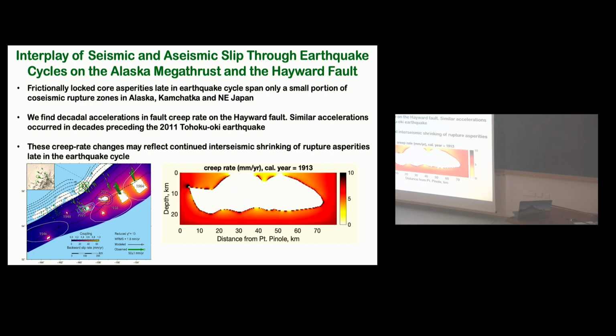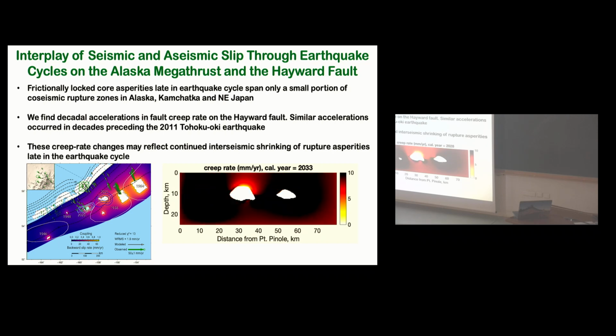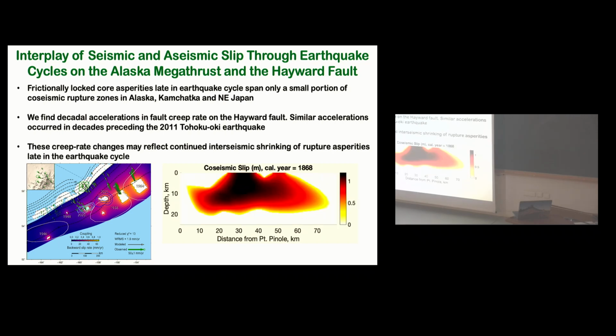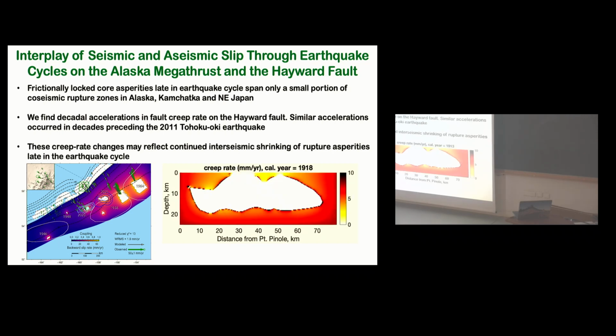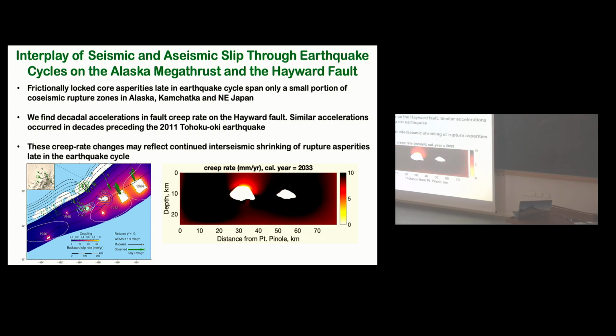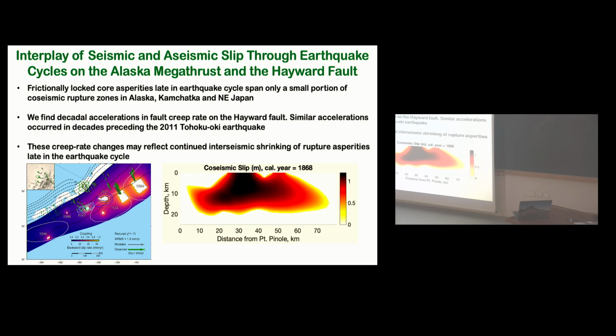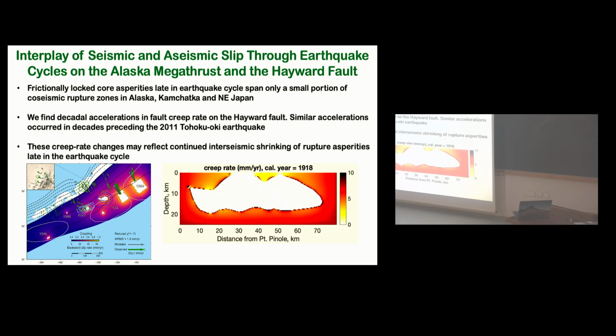So in principle, you could have frustrated instabilities prior to the earthquake, so slow slip events in this eroded part of the velocity weakening patch that would register as an accelerated slow slip, which is not necessarily a reflection of shrinkage. Shrinkage could be a much slower process to account for this gradual acceleration of slip just due to the change of the coupling on the fault.